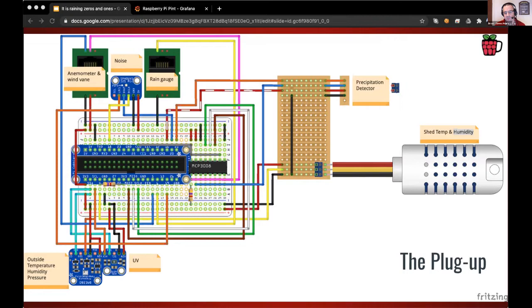So I wanted to make it PoE powered, so I could just drop the Pi probably in my loft and then just run a bit of wire outside for the exterior sensors. The original project uses a DS18B20 ideally to do the moisture reading from the soil, with that kind of schools education kit. I was going to put this at the top of my house, not a lot of soil up there, so I thought what I'll do is swap that out for the DHT22 and pop that inside my loft, and that would give me a reading from in there. So I thought, right, this is a good plan. This has got legs. It's going to work.